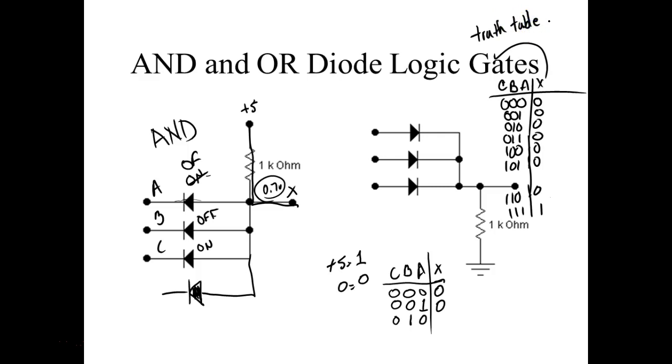What a truth table does is it shows us how the output responds to every possible combination I can put on the input. Now notice all we're doing on the input is counting, right? You understand that? And you can tell how many entries you got in it. So I have 3 bits, and you can tell how many entries you have just by taking the base. This is base 2, and then raising that to the number of inputs.